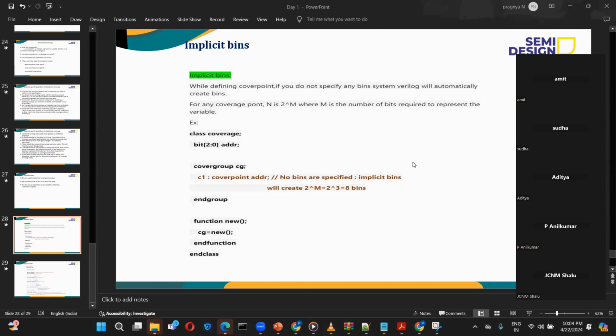And then why do we need functional coverage when we had an option of just creating test cases for a particular feature, but why the functional coverage has got more significance? What is directed verification we saw, and what is constraint random verification? How the coverage is related to the constraint random verification? All this we saw, and then what are the things which we have in the functional coverage? Means if we want to write a coverage file, what exactly some idea we should have, like covergroup, what are coverpoints we saw, and then what are the coverage bins? What are the different types of bins we have? And what are the industry specific guidelines to create a functional coverage? So all these things we have gone through in today's session.